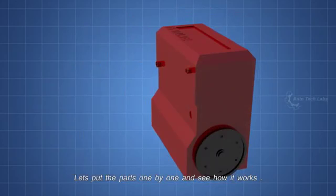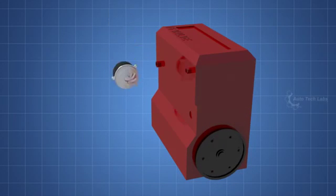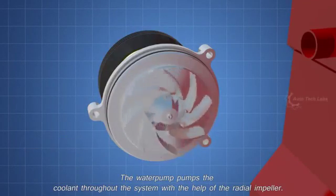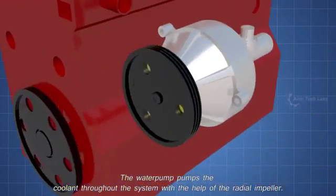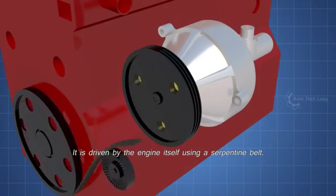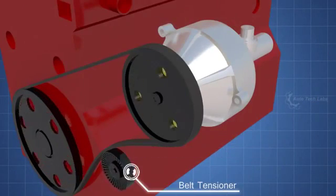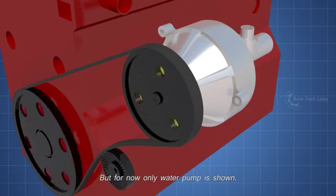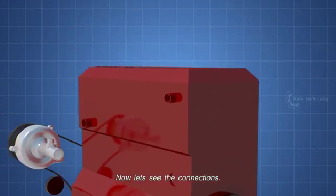Let's put the parts in one by one and see how it works. The water pump pumps the coolant throughout the system with the help of the radial impeller. It is driven by the engine itself, using a serpentine belt. The serpentine belt also drives the power steering pump, alternator, and AC compressor. But for now only the water pump is shown. Now let's see the connections.